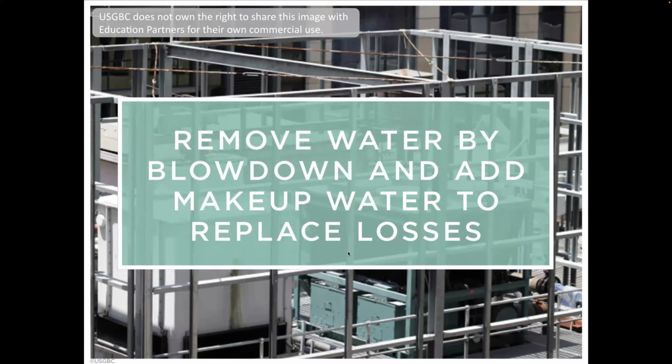And so they have to do what they call blow down the water. So they basically just flush the whole system of the water in the system and then replace it with more potable water. So if you can minimize the amount of times they have to do that in a given time, they call it cycles. So if you have to go through 5 cycles, then you have to blow down. If you can make it to 10, you're saving a lot of water because you're doubling the amount of time before you have to blow down the water. So that's kind of the terms they're using here.